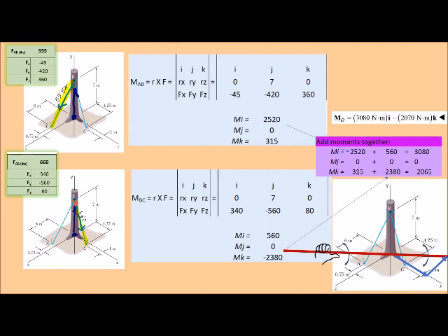Same thing for the next cable. Which way is this cable trying to rotate? So remember, this one's kind of pulling in the X direction, and that's going to rotate it around the Z direction. So you'd expect for this to be the large magnitude that this guy's rotating it around. Okay, so once again, we're coming down the tree trunk. Axis of rotation, to where the force is applied.